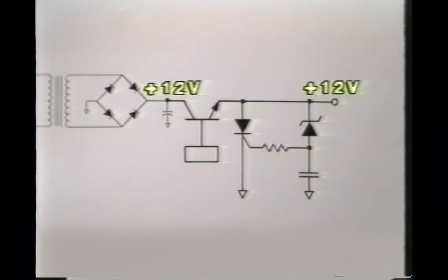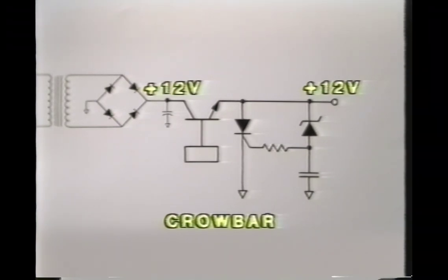To prevent a shorted regulator from damaging the computer, some game manufacturers have included a circuit called a crowbar. The crowbar circuit is made of the Zener diode and the SCR with a small handful of other components. Under normal circumstances, the Zener diode will not be conducting. It's a 5.6 volt Zener, and a normally working power supply like this will have an output of just 5 volts.